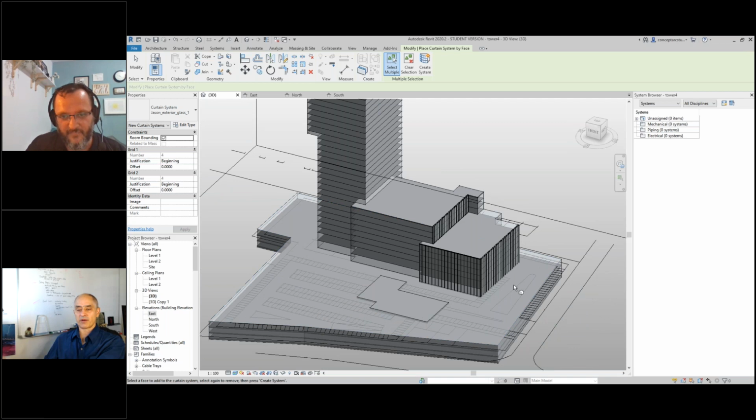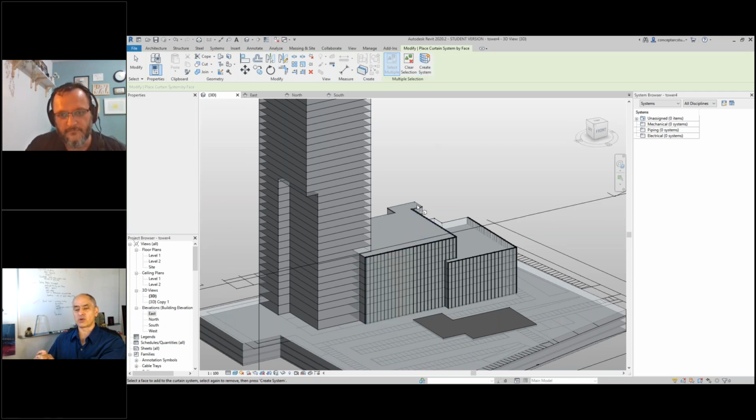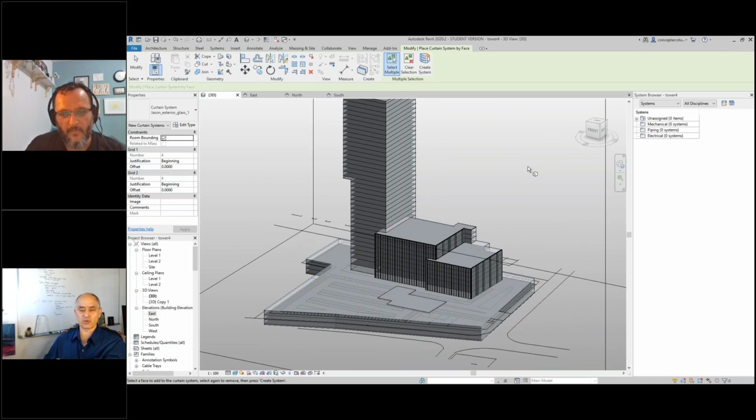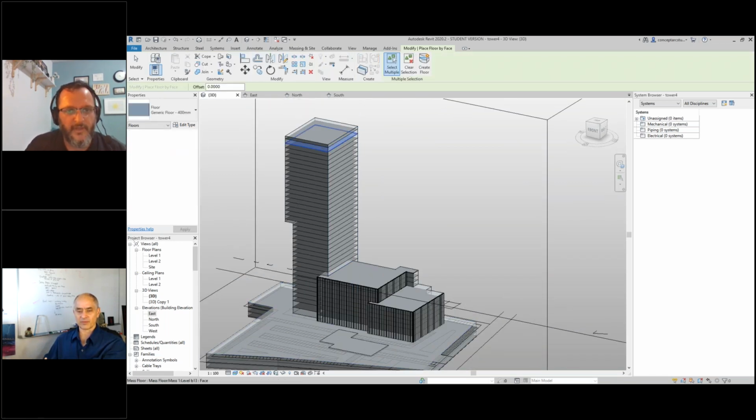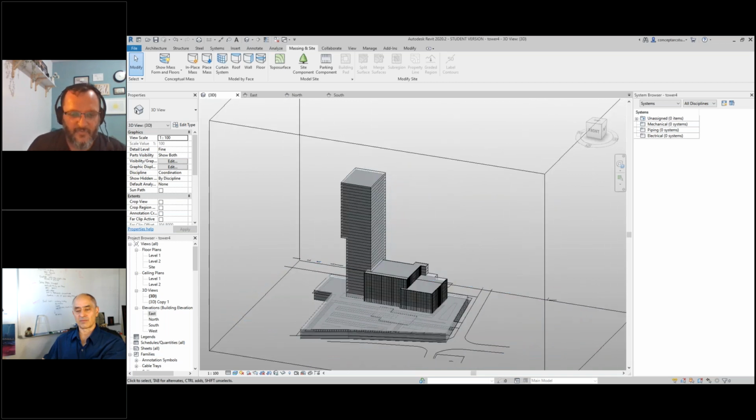Mm-hmm. Okay, so then what is the benefit of going back into SketchUp, and what if you were to add some things into SketchUp? I guess you're not going to be spending time adding entourage and bringing it back into Revit. Is that right? No, we do not bring the model back into Revit. The final model lands up in SketchUp, the entourage in SketchUp. Revit gets used solely to model the structural elements of the building, and you can say SketchUp in the end of the process gets used to embellish the model with trees, cars, people, aeroplanes, buses, trains, landscape. So the landscape and the context is for SketchUp. The model and refining the model is in Revit.